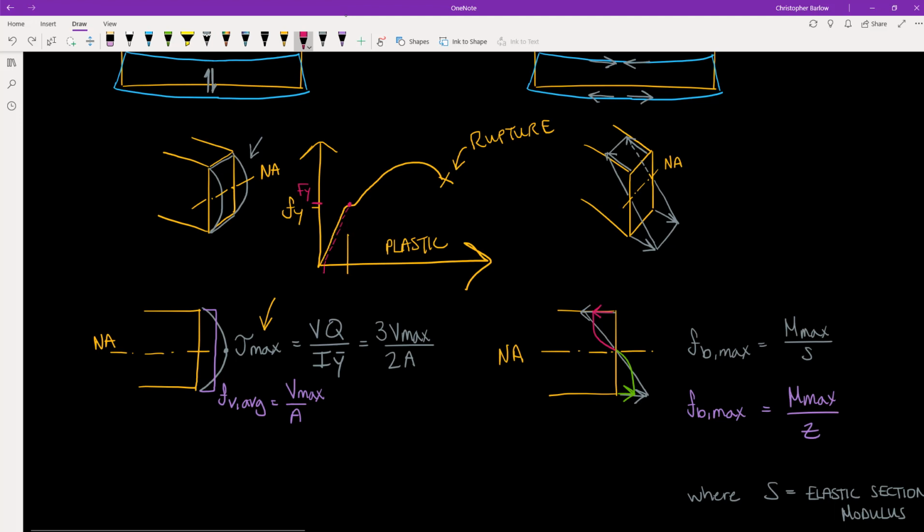And that offset is defined by a plastic deformation of 0.2%. And so we are actually going to allow just the slightest amount, 0.2%, of plastic deformation in steel design when designing for ultimate or factored loading. That slight bit of plastic deformation allows us to simplify our calculation of our demand stresses.